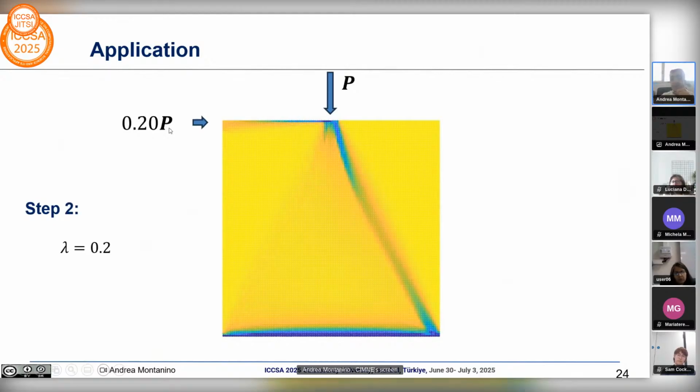If we increase the horizontal load, finally we get load multiplier 0.45 can be extended until 0.5, and we see that this diagonal band vanishes, and the final internal structure that develops inside the masonry panel is represented by a horizontal bar and a diagonal bar until the right lower corner of the structure.